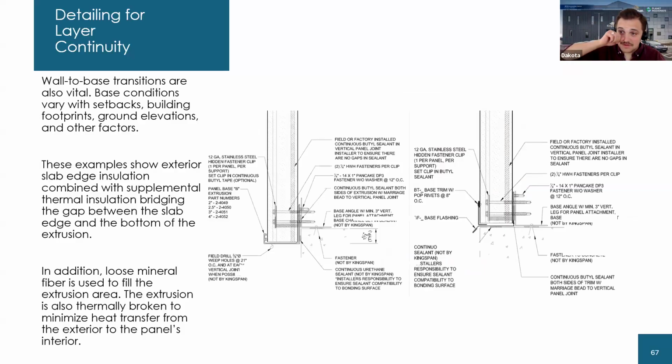Spanning, it's just steel, insulation, steel. There's not much of a section detail between the roof and the base, but when we get to the base, we have a few conditions to consider. When we meet the slab, we have two methodologies that we can use. The first one, we have additional steps we'll talk about in the next slide, but if we're doing bypass framing, that IMP is going to go past that slab base there.